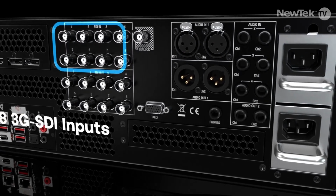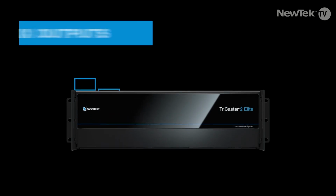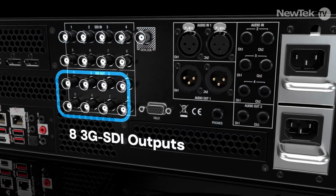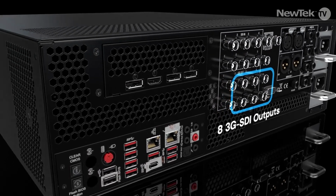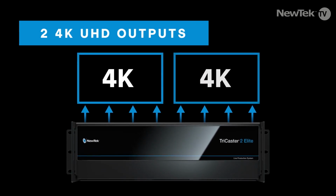TriCaster 2 Elite features 8 1080-60p 3G SDI hardware inputs to connect to traditional video equipment like cameras, video routers, and media players. Once your show is ready to deliver to your audience, TriCaster 2 Elite gives you more options than ever to distribute your content. With 8 individual inputs, you can produce multiple video programs from one system. Then output your show through the 8 1080-60p 3G SDI hardware outputs for connecting to monitors, projectors, video walls, digital signage, and more. These connections also give you the flexibility to output 2 4K Quad-Link Ultra HD connections.